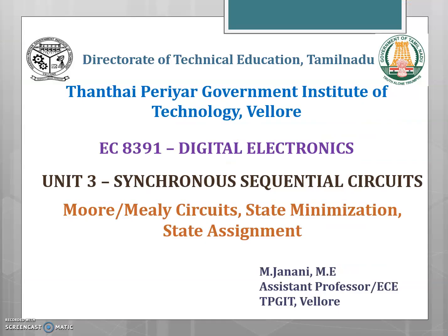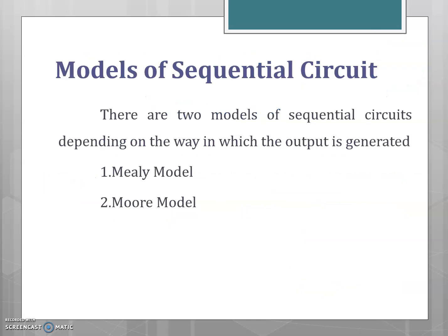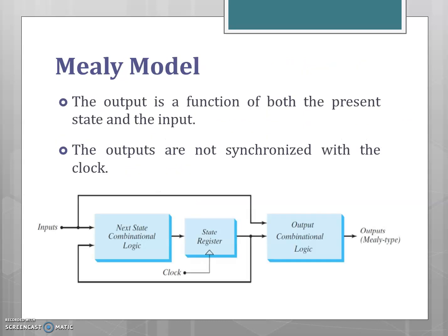Hello everyone. In this lecture, I will be discussing Mealy circuits, state minimization, and state assignment. In sequential circuits, there are two models depending on how the output is generated: the Mealy model and the Moore model. In the Mealy model, the output depends on both the present state as well as the input.